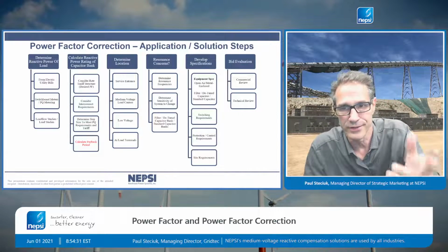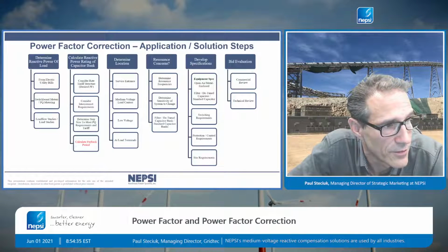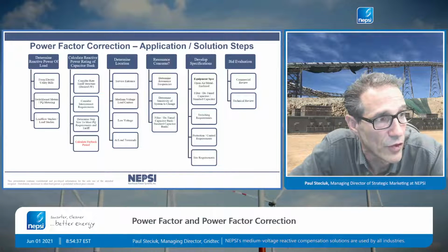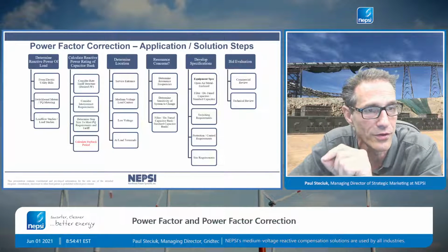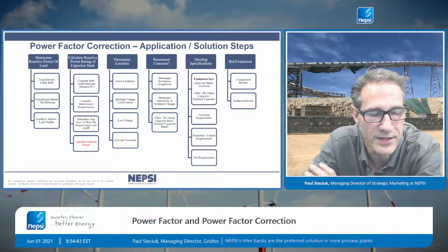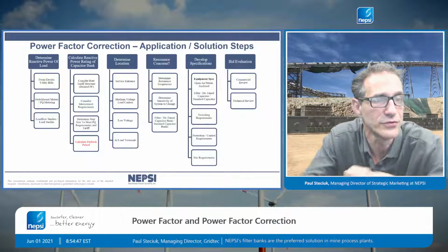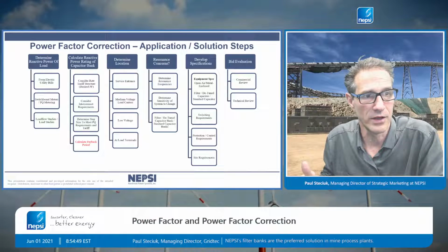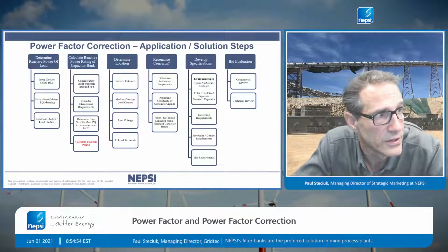It used to be, back in the 90s when I started working in power systems, that a capacitor was often placed at each and every motor within an industrial plant. That philosophy is no longer followed. Most often, larger capacitor banks are applied at the load center rather than at each individual load.